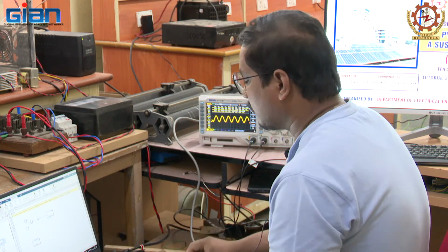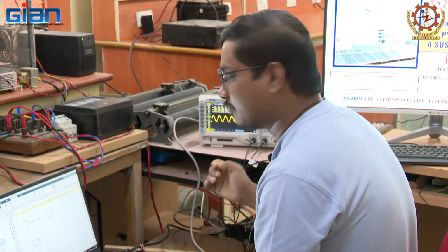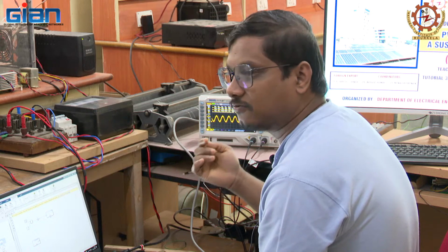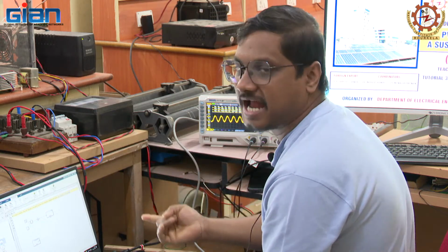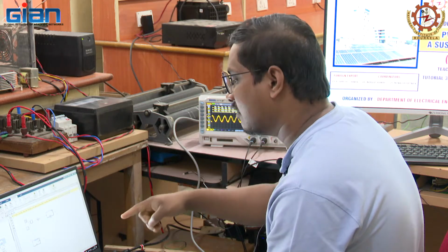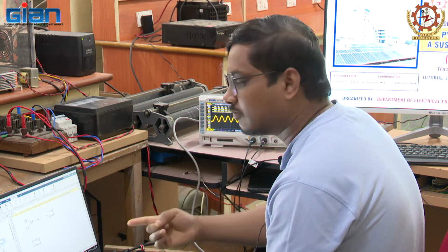Here we do not have any physical analog signal or practical scenario from outside. So, to read the ADC, I am giving the value directly from the DAC. We can give this as an ADC pin also. So, I am using DAC A as the analog input to my ADC.